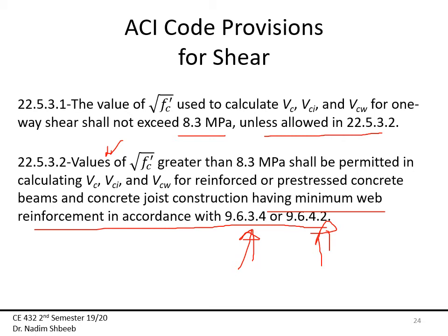So what we discussed so far is we had an idea of how the shear strength or shear resistance in reinforced concrete beams is calculated: we said it's coming from shear from steel and it's coming from concrete. Also, we set where we are going to calculate our ultimate shear. In flexure, it was easy. We always go for the maximum moment. For shear, it is not.